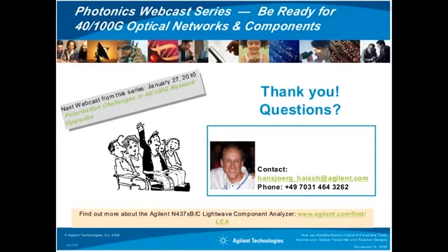In reality, we have enough confidence that by properly employing electronic calibration methods, where the calibration is basically determined by the electronic calibration that you do on the electrical interfaces of the LCA, you can basically be independent of the network analyzer.